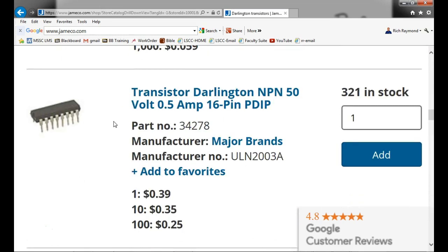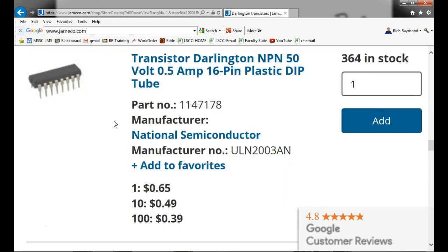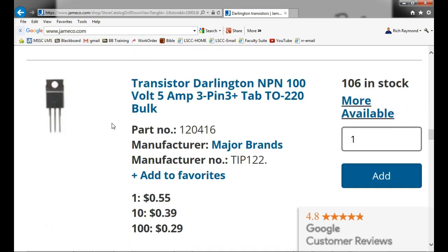There's a thing up on the Motorola site that shows most of the standard outlines. These are JEDEC registered. All you've got to do is make your circuit fit inside that package. And they've got them there, so TO-3, big guy.